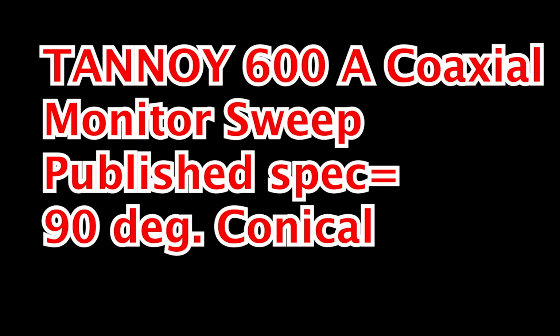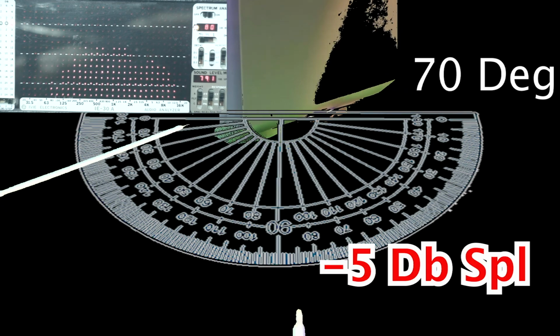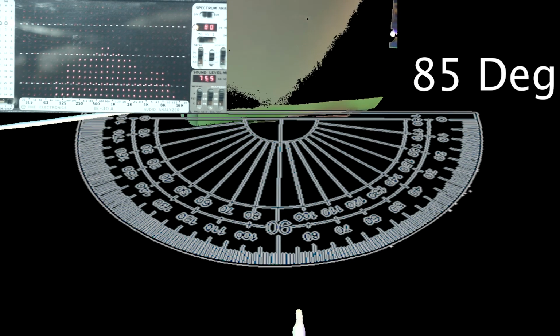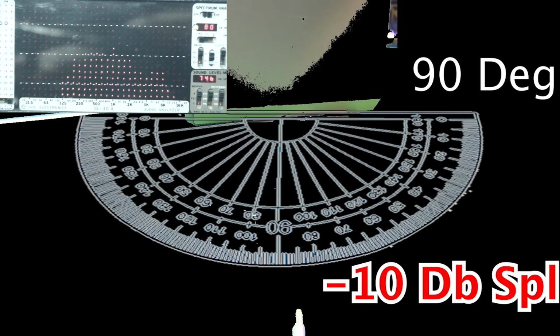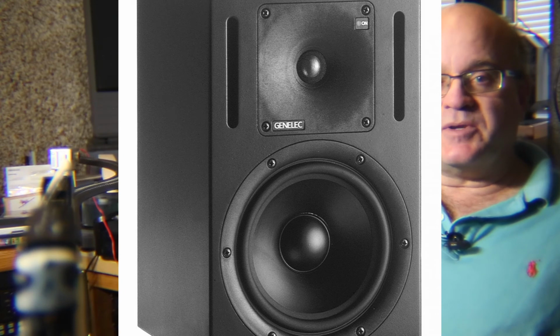They allow you to alter the tuning of the cabinets according to your needs. As we measure the fall off of the speaker, we see that it occurs at exactly 45 degrees, which represents a 90-degree horizontal dispersion. Because of the symmetrical design of the speaker cabinet, it will also be 90 degrees vertically, and the actual published specifications of the cabinet are listed as 90 degrees conical.